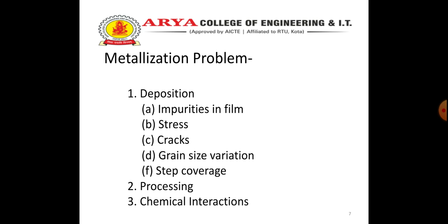Now, afterwards, we are having chemical interactions. Metallization can be completely destroyed by reactions induced by thermally activated processes with the substrates or the layers on the top. Pure silicide films on polysilicon or silicon are fairly stable in their metallurgical interaction with the substrate.